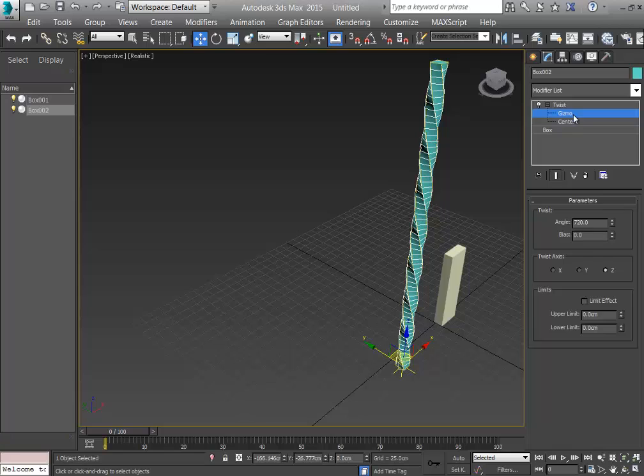And if I click this gizmo, that is the sub-selection mode, meaning you are selecting a part of the twisting function now. In this twisting function, I want the twisting action to start after 150 centimeters. So once the gizmo is selected, I raise the gizmo up by 150 centimeters.